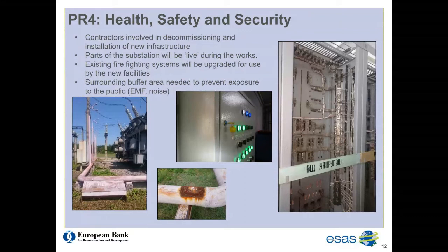The safety procedures for work on energised systems are old and in need of update. Notably, there is no permit to work system. Furthermore, tag out and lockout, a common good international practice, is not used. Instead, wooden barriers are put in place to prevent workers touching live electrical apparatus, as you can see in the right-hand photo. A good tagging system to advise workers of the status of equipment is essential, as is a lockout system which guarantees isolation, especially when contractors are unfamiliar with the site.